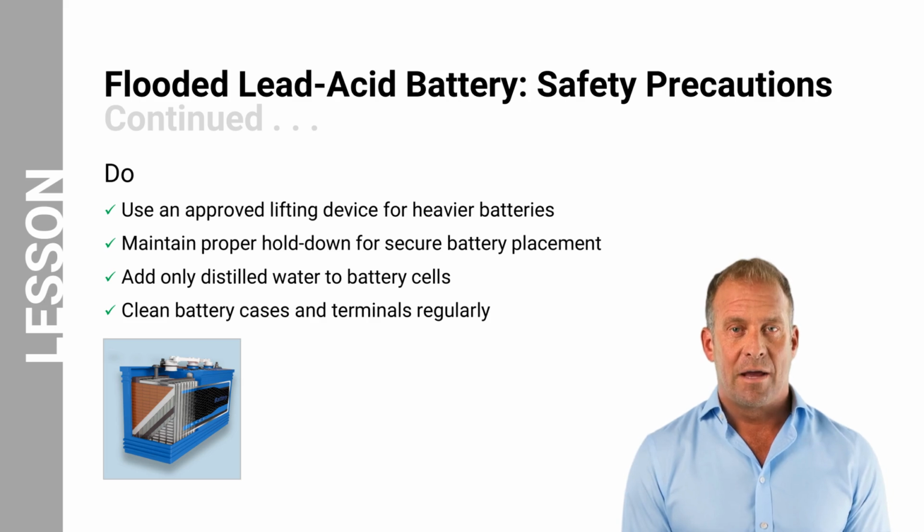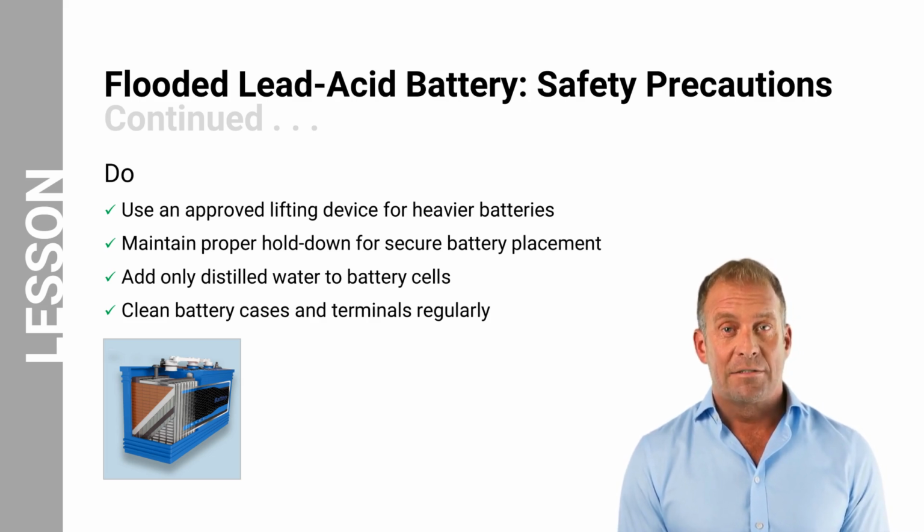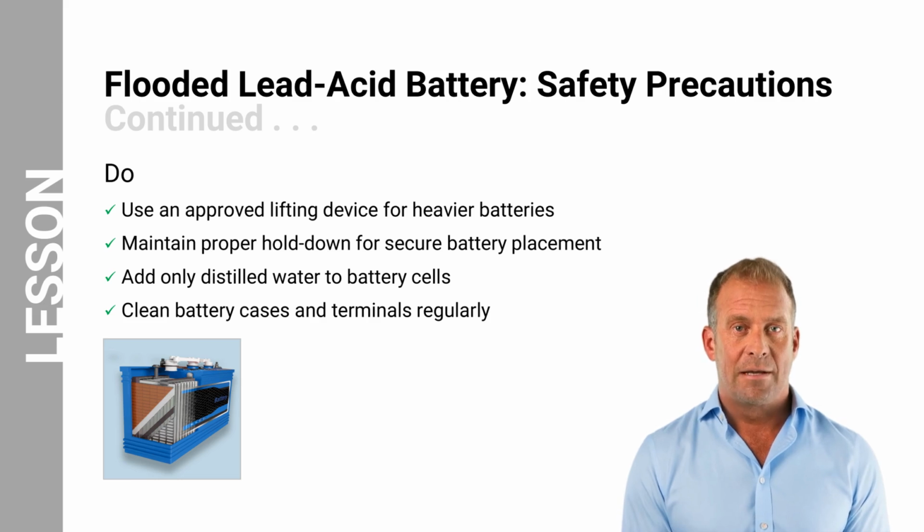Utilize a lifting device for heavy batteries to avoid injury. Maintain proper hold down for secure battery placement during transport. Only add distilled water to the battery cells to maintain electrolyte levels. Regularly clean the battery case and terminals to ensure optimal performance.